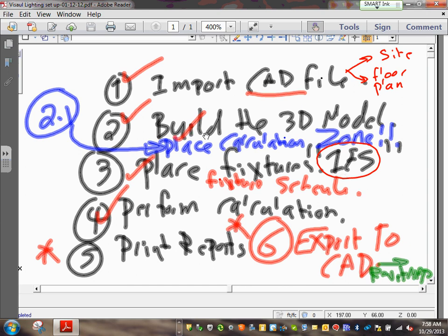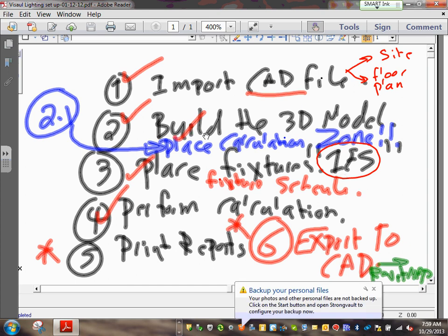And after we export to CAD, because we're doing Revit, what do you need to do? You take it from CAD, then import CAD to Revit, and then you start your Revit project. You can see how things are tied together. Now when you export to CAD and import CAD into Revit, it becomes exactly like the Revit that you're working with, guys. Instead of tagging a receptacle, you have a lighting fixture; you drop a fixture in Revit. Fixtures are there, families, and then we circuit it, and we tag it, and we switch it. Can you guys see the big picture? Karen, do you see where we're heading? Why are we doing this?